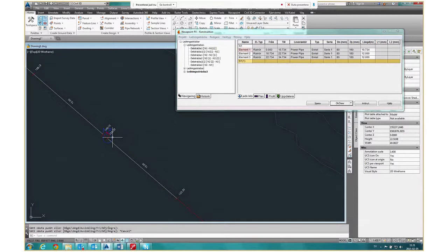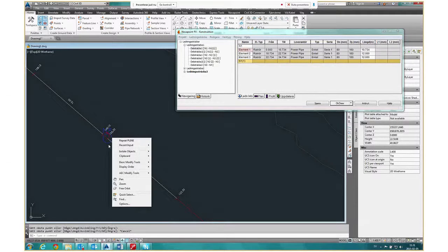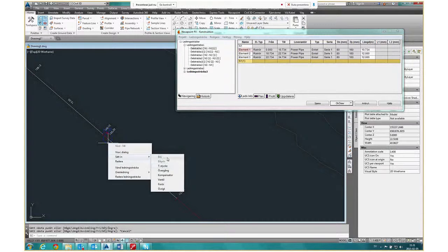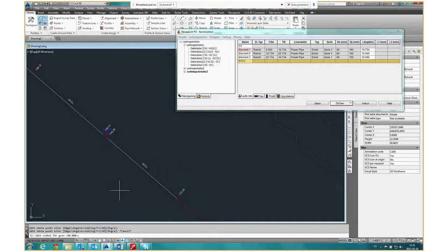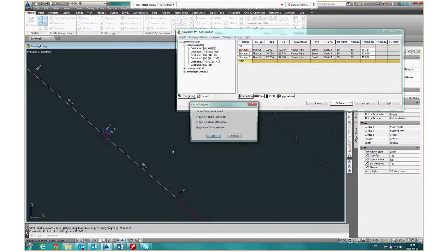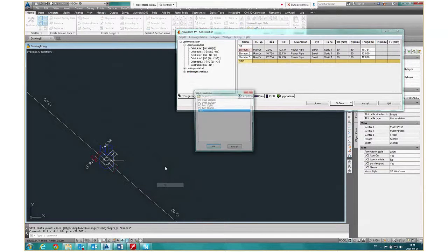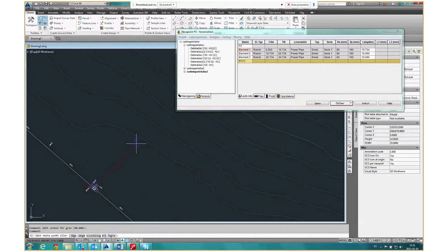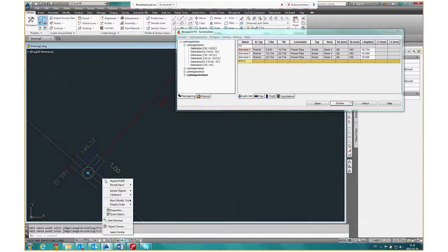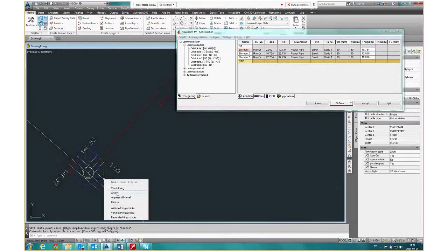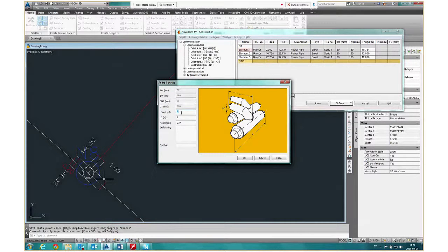If we check at the T-cross pipes, we can just right click on a node and put in a T-cross and 90 degrees. It looks like this. And from the T we can just right click on the node with a new section that goes out from that cross, like this. And if we just right click on the T-cross, we can see how it looks, and we can change the length of some of the elements here, or the height.